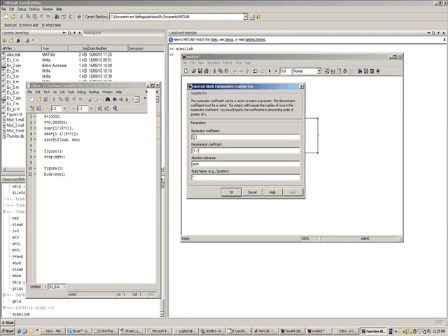Inside this vector, you define your numerator polynomial as coefficients. So your s term will be 0, and then it will be 1 upon RC, but R and C values will not be transferred to the Simulink block.